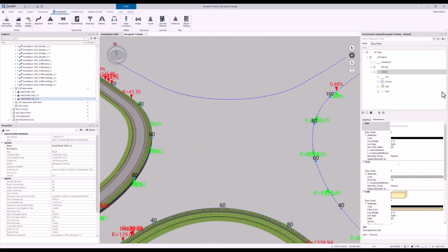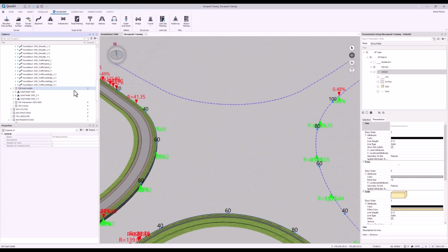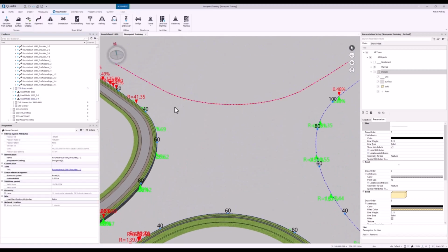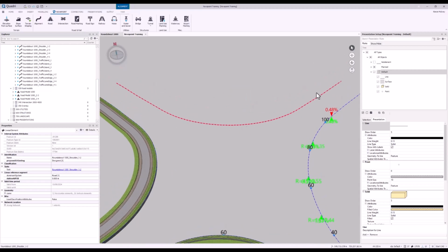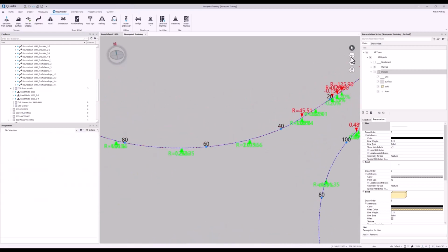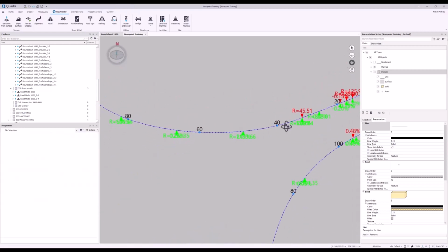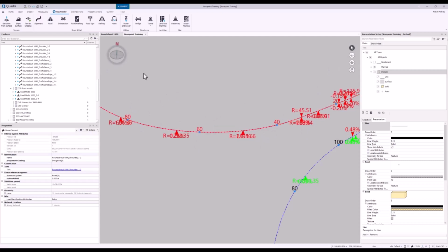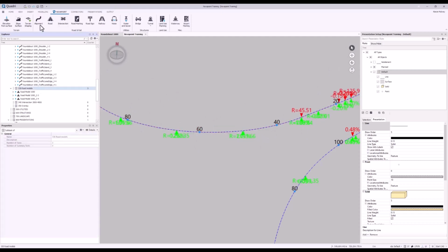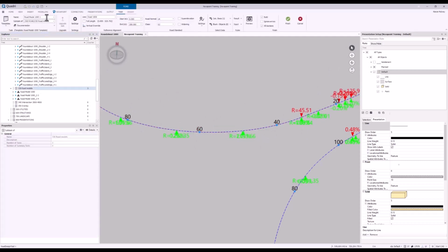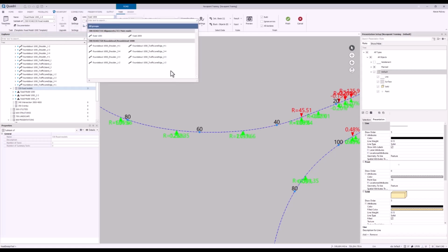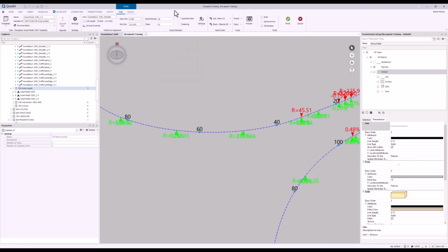Now for the final two. So let's select this one, and this is shoulder 1, 2. Just zoom in a bit so I can see the direction of the alignment. So we can see the left hand and the right hand side there. Perfect. Now I need to create my road task. So Novapoint Road, do 1, 2, change the line that I'm using here.